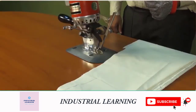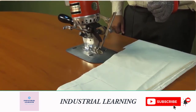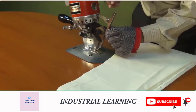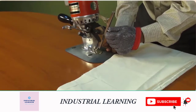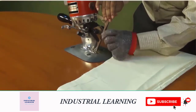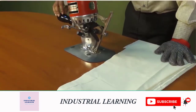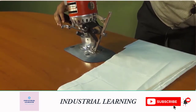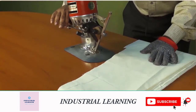The height of the cutting can be controlled by adjusting the height of the knife guard. This is the knife guard. By loosening this screw and either taking it upward or downward, we can adjust the knife guard height. After that, we have to tighten the knife guard. The sharpening of the knife is activated by pressing the lever.